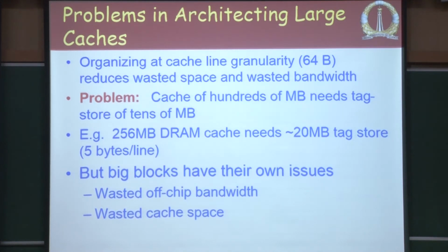But the disadvantage there is that if you have a large block, you would bring that large block from the off chip DRAM to the on chip DRAM cache, and that would waste your off chip DRAM bandwidth. It would also mean that if there is not enough spatial locality, the data that you bring in may not be very useful, because when I am bringing in, let us say, 2 kilobytes of data from my off chip memory to my DRAM cache, that is a significant amount of data, and I may not necessarily use all of it, which means there is wasted bandwidth as well as wasted cache space.